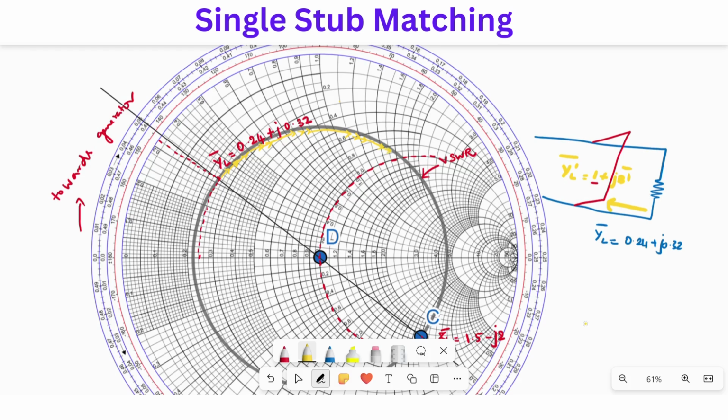So the point is right here. You have to find out what the admittance is right here. I'm just going to write it down here. YL bar is equal to, the conductance being 1, and the susceptance is 1.7, so plus j1.7. Now this distance will give me the position of the stub, and I'm going to denote this distance as S.